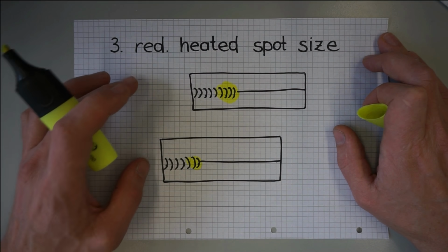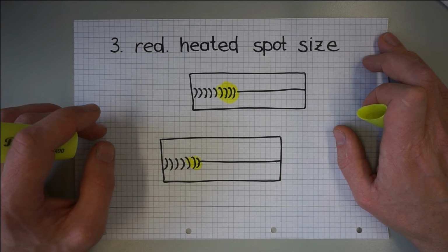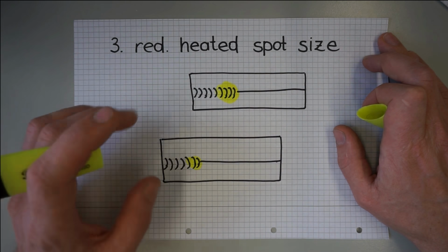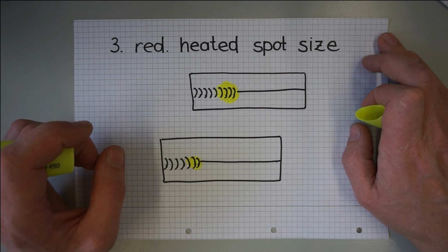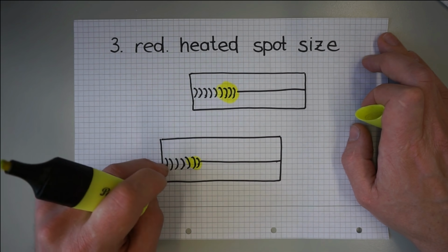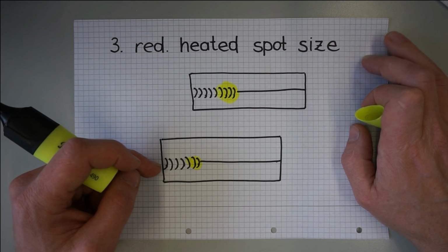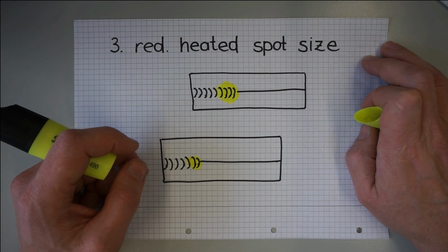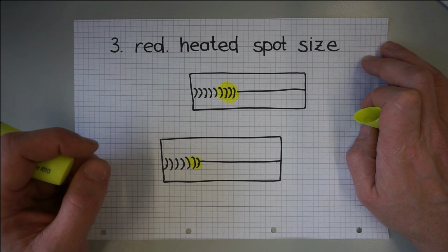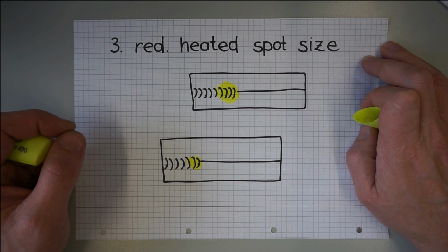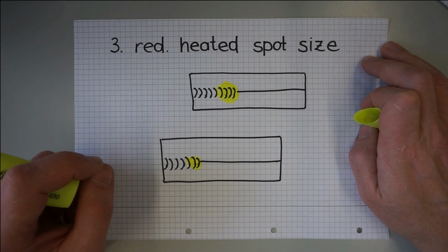Process developers and welding equipment manufacturers already did their part in this and established welding techniques with so-called higher energy density. This results in smaller heated spots for a given weld bead size. So in terms of distortion, TIG welding, for example, is better than oxyacetylene welding because the former focuses the heat much more. But this is not the end of the line.